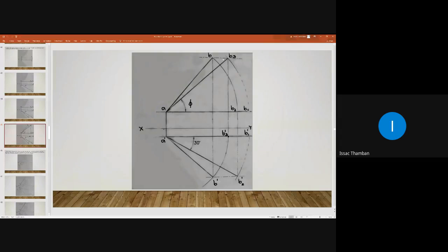Then after that, you can draw this locus plane, and from B3 dash you have already drawn a vertical projector. This locus plane will intersect here, and that is point small b. You connect AB, and that is our final plan. And that is the solution. And I am concluding here.